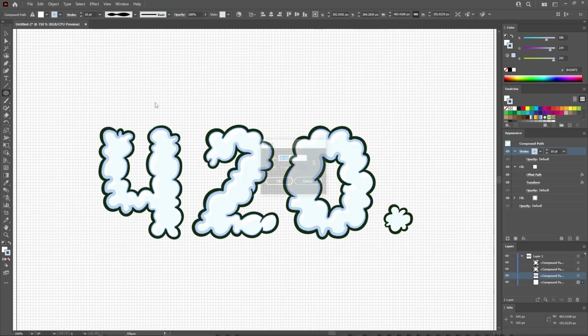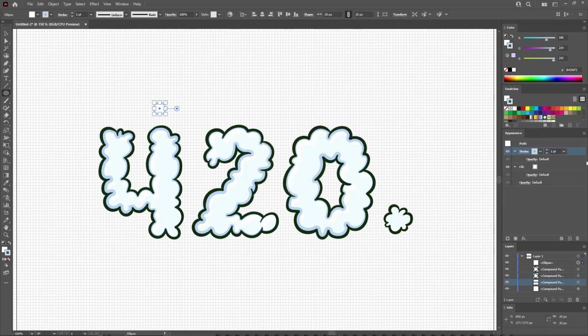Simply click on your artboard to create a 20 pixel circle. Select the stroke and remove the color. Select the fill and replace the color with 166, 223 and 232. Use the selection tool to move this shape in this location. Hold down the Alt key and drag a copy in this position and another copy in this location.